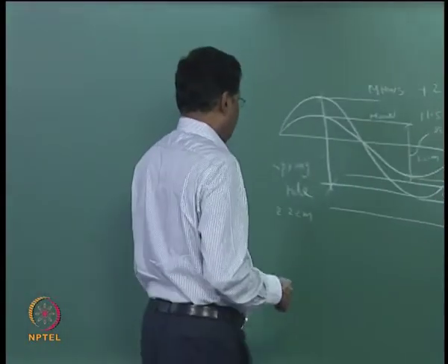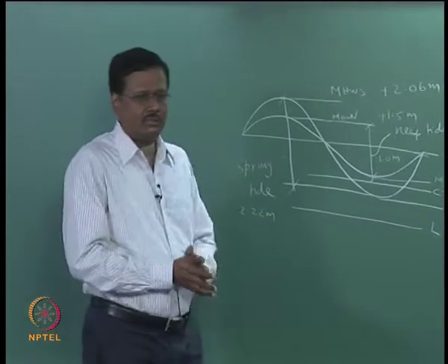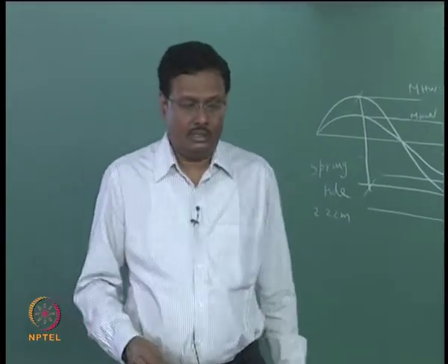In an outer harbour on the seaside, generally the chart datum is the lowest water level. Where you have large tidal variation, or where the harbour structure is in the inner lagoon, your low water level can be below the chart datum. This water level is very important for design purposes, to calculate the differential water pressure as well as the dredge level.